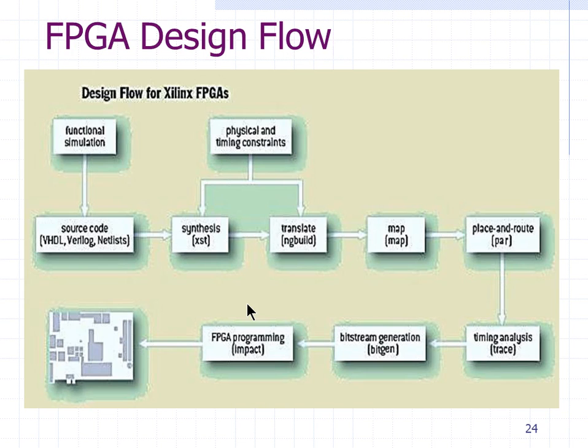It's actually the back-end part which is more complex, but that's how it works, because the back-end part is done through a lot of software. Very little manual intervention is required in the back-end process. A lot of back-end tools from Cadence, Synopsys, even Mentor will be used by back-end designers, who are called physical designers. But the front-end part, where you do Verilog design, Verilog test bench creation, functional simulation, and verification of the design, will take 60 to 65% of the design time. Since it takes more time, you need more people in those areas.